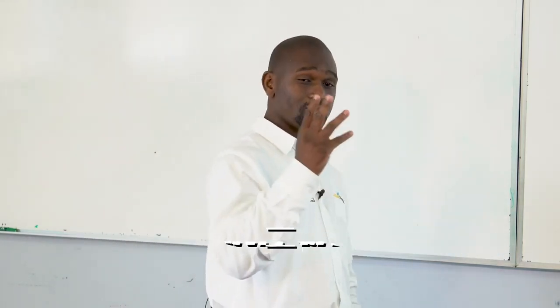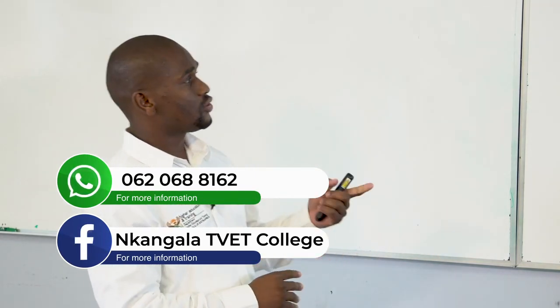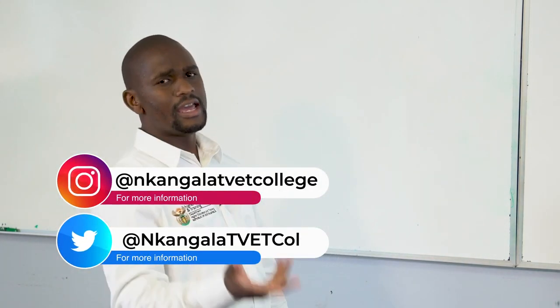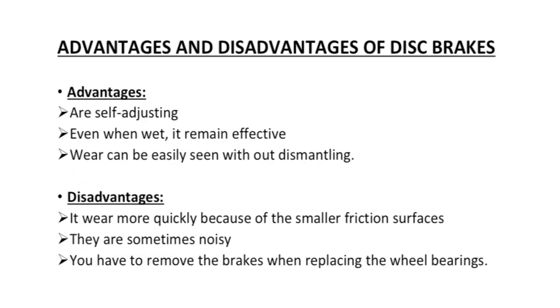Remember we said we have 4 types of brakes, that is disc, drum, electromagnetic, as well as the thruster. So these brakes also have advantages and disadvantages. Advantages of a disc brake: number 1, they are self-adjusting. Number 2, even when they are wet, they can still work and remain effective. Wear can be easily seen without dismantling the brake. You can easily see wear on this type of brake.